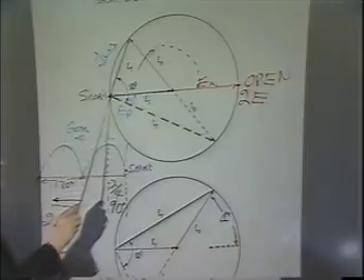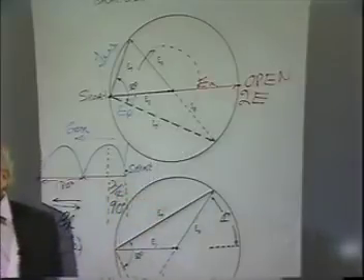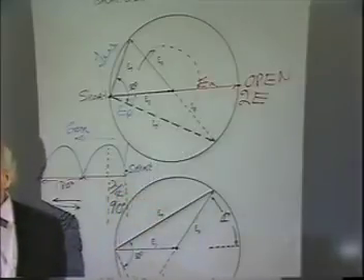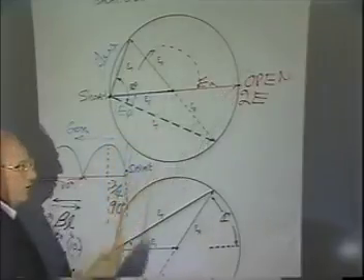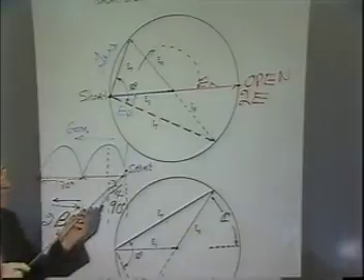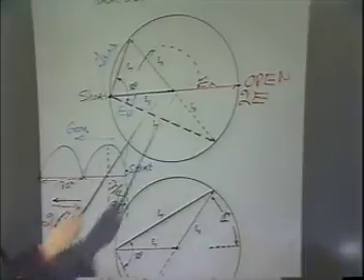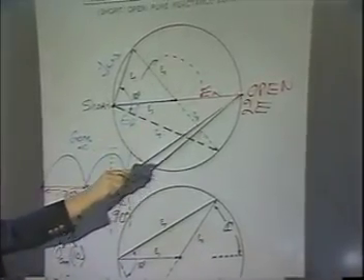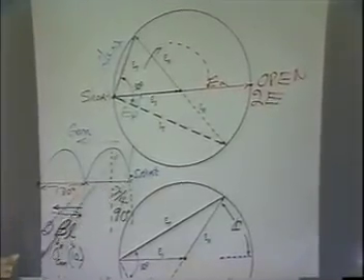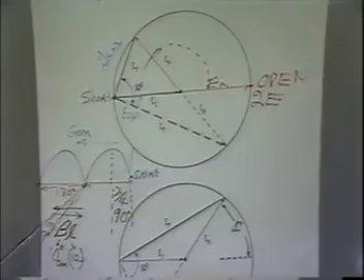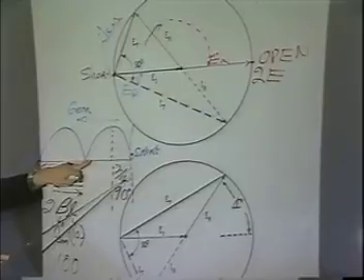What's the distance between here and here in terms of fractional wavelengths? 1/4 wavelength, isn't it? So here you see that from 0, 180 degrees travel is 0.25 wavelengths because you're traveling from here to here, 1/4 of a wavelength. When you go all the way around this chart, how far have you gone? From the maximum all the way around over to here, back to 0. So you went to the maximum and back to 0. So the chart over here represents only this 1/2, doesn't it?